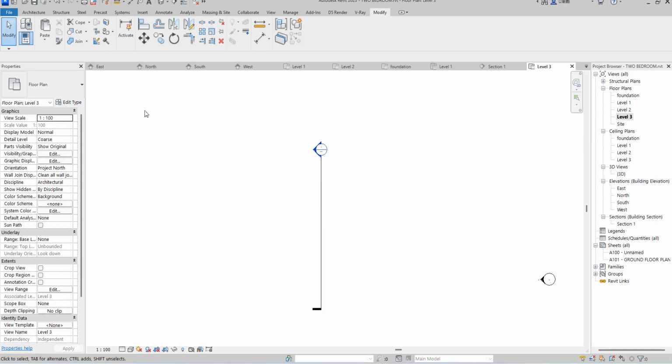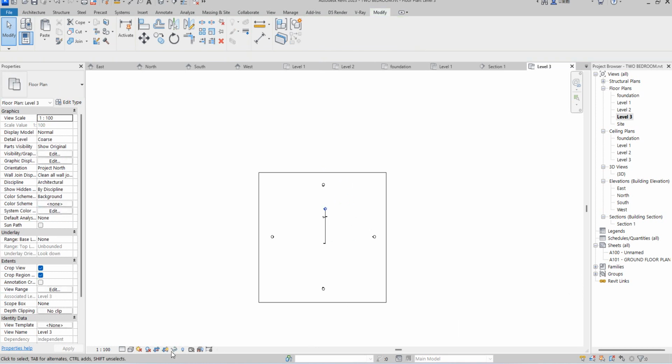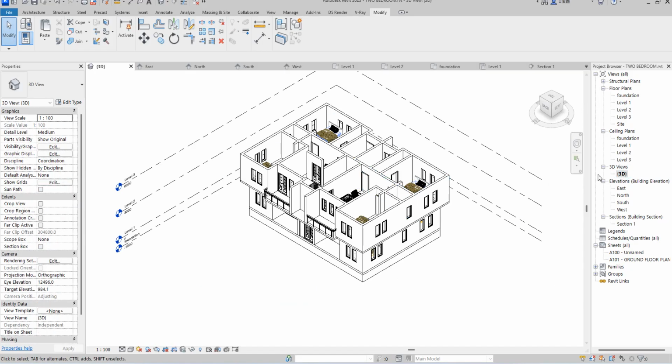Here you just click as you have done. You just come here and say align to current view. It's not visible. The reason it's not visible is that the crop region is hidden. So click on the crop region. What happened? Something is missing. Did I select only one? Okay, my issue is I only picked one.